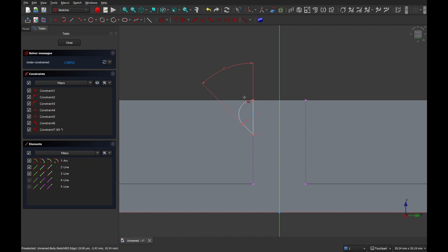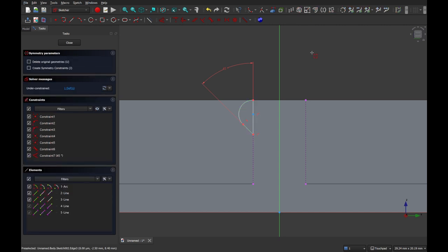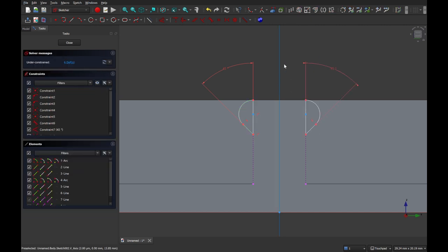But now you also want to put this on this side. So if we select all of those lines, we can do it on the left hand side here, or we can box select everything like that, but don't do it that way because you end up with this line. So if you do it from the top left down, you just get the lines you want to do. And then we can mirror. We can use the mirror up here. I mean, you could just redraw them all and then just make everything equal, but if you just mirror around this one, there you go.